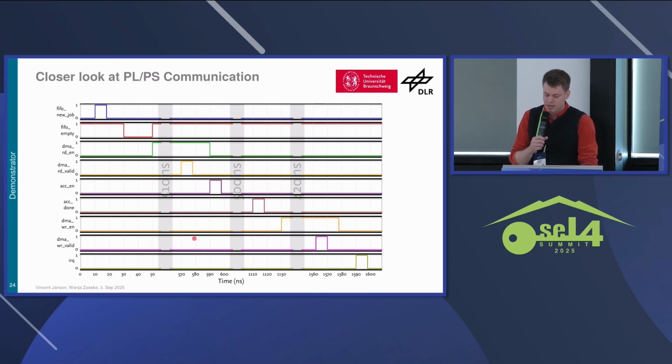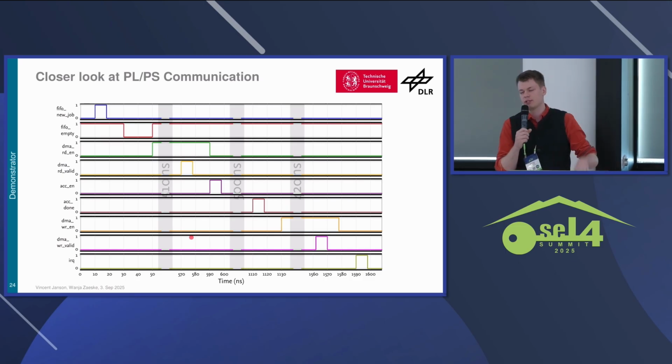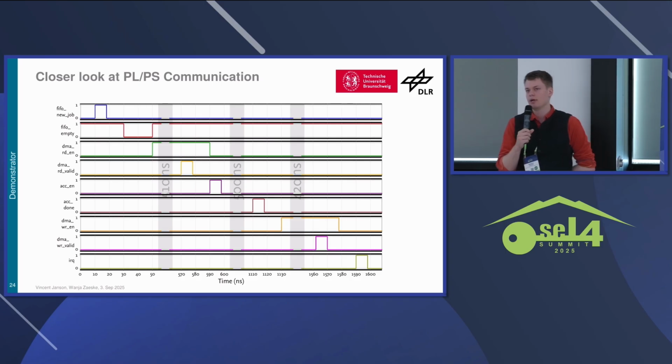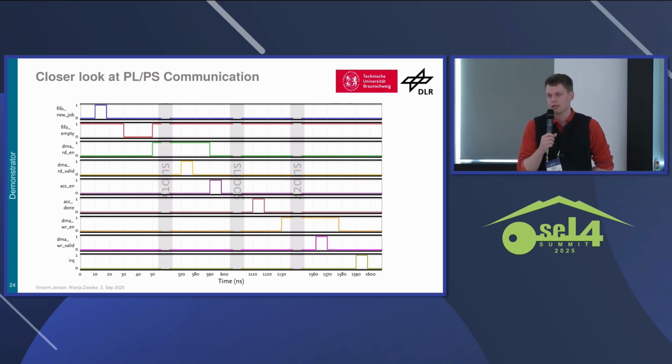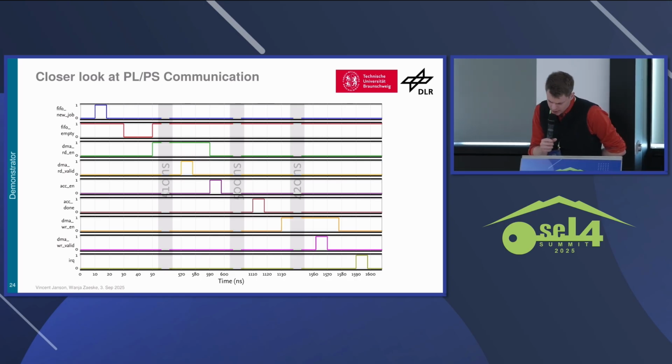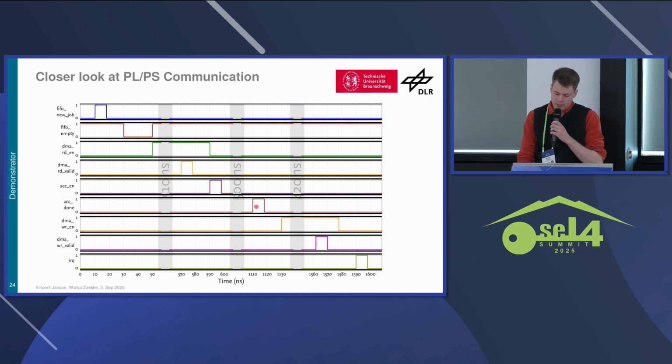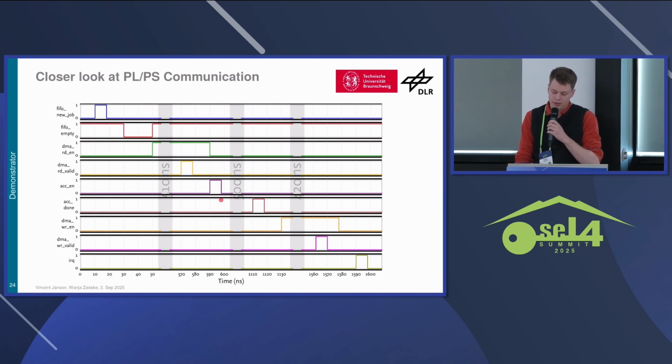And for the amount of data that we have, that works out to somewhere around 120 megabytes per second, but given the width of the DMA engine, we would expect it more to be in the vicinity of 380 megabytes per second. Other than that, we can see that there's a quite reliable 500 nanoseconds delay of the hardware accelerator dummy.